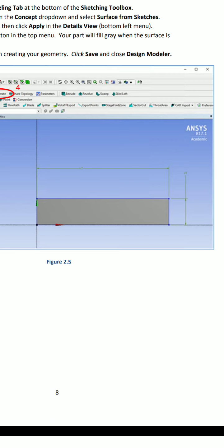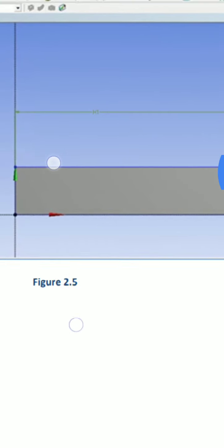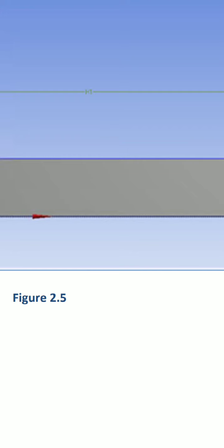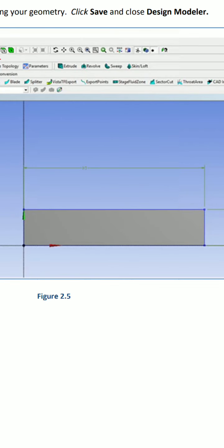Suppose you are modeling a wind tunnel section, where you are keeping an aerofoil or any object inside, like flow over a circular, a square, or a triangle. So anything you can create in the center portion. In the center portion you can draw one more rectangular section. Then you can use the surface option, pick the 2 edges, and automatically the center portion is hollow. The center portion is not filled. Your object is not filled; only the remaining fluid medium needs the surface.